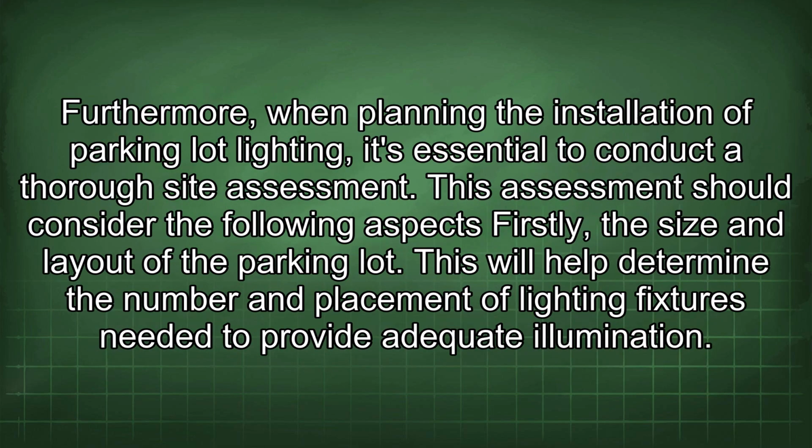Furthermore, when planning the installation of parking lot lighting, it's essential to conduct a thorough site assessment. This assessment should consider the following aspects. Firstly, the size and layout of the parking lot. This will help determine the number and placement of lighting fixtures needed to provide adequate illumination.